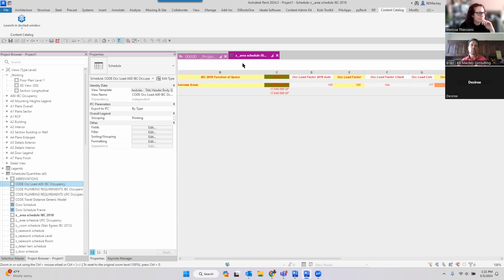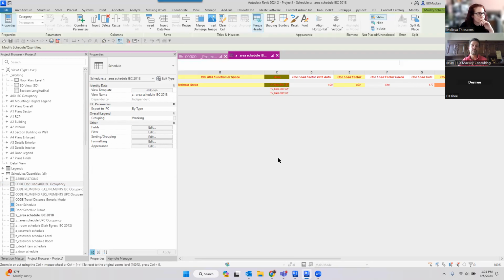So for me, that's one of the things I often do, is go into a lot of my clients' files and rename the views, break what it is up here just by hitting the clear cell and then putting what they wanted in the title. So we can use that to get our schedules grouped a lot more logically than just how you wanted the title to say.